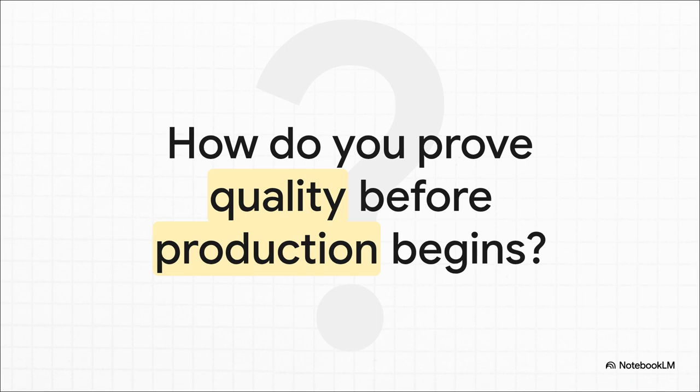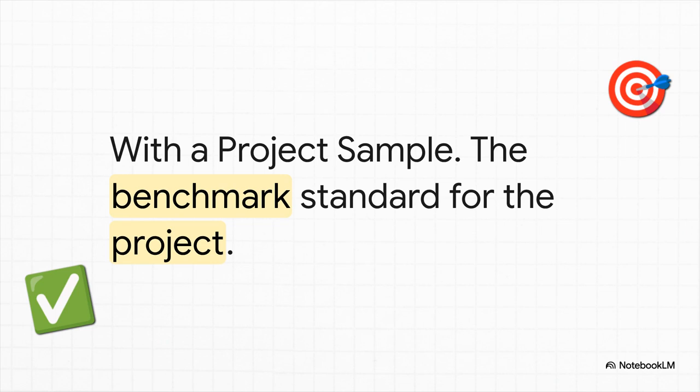So let's think about this for a second. In any big project, what's the single biggest risk? It's that gap, right? The gap between what the client pictures in their head and what actually gets delivered. That's the problem we have to solve before a single production panel ever gets poured. And the answer? It's the project sample. You've got to think of this thing as more than just a chunk of concrete. It's a physical contract. It becomes the benchmark, the one single source of truth for quality and appearance that everyone on the project agrees to.